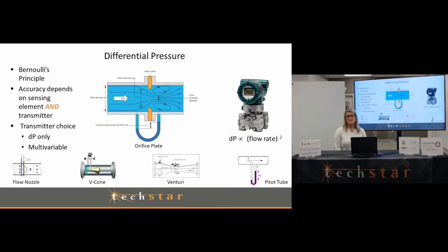So Bernoulli's principle states that as the speed or velocity of a fluid increases, it's inversely proportional to the static pressure. So that means that a pressure drop will occur over a restriction. So if we look at the picture right here, there's an orifice plate, and as the flow increases, there's going to be a decrease in pressure, so a larger pressure drop over that orifice.